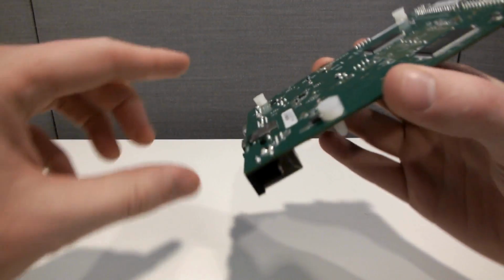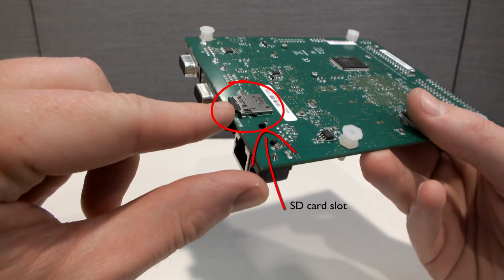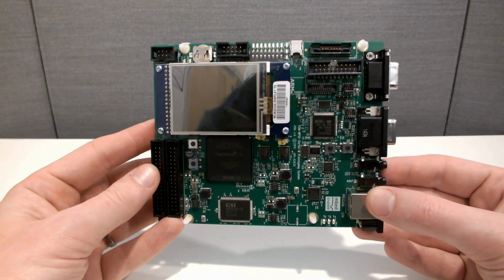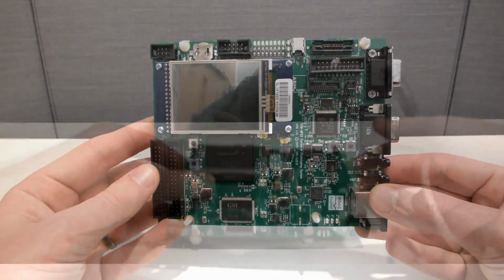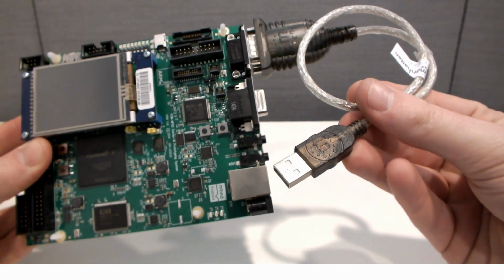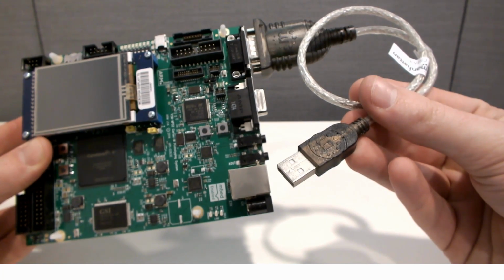It's supplied with a preloaded SD card containing the boot files for the motherboard, shown here in the SD card slot on the back of the board. We don't need to change this card for DesignStart prototyping. Instead, we'll upload new files to the card. The board has a UART to USB adapter that connects to the UART general purpose connector here. This outputs printf messages for you to view in a serial communication viewer.